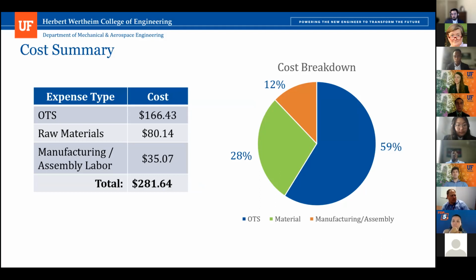I think our main thing was the galvanized steel backplating for the reflective subsystem. We were considering changing it to injection molded ABS because that would be way cheaper. The reason we didn't is because then you run the risk of even more plastic in Las Vegas heat. That's where we're looking to make the most changes, because as far as raw material goes, I think the galvanized steel is the most expensive component.